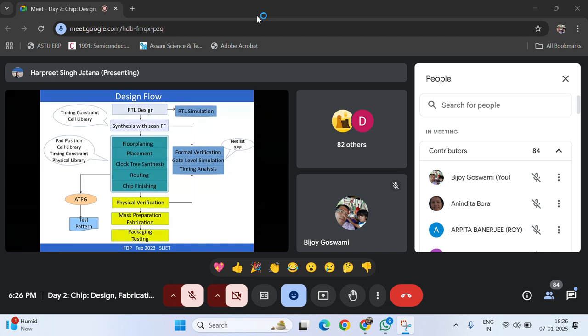So IO pads are normally like a standard cell library. The IO pads are also given along with the IO cells. So all these technology files and timing related information, then their model parameters, all that information is there in the foundry on which we have designed the circuit.